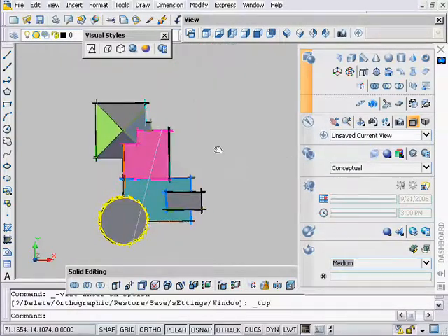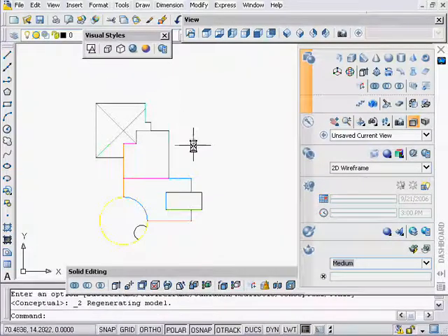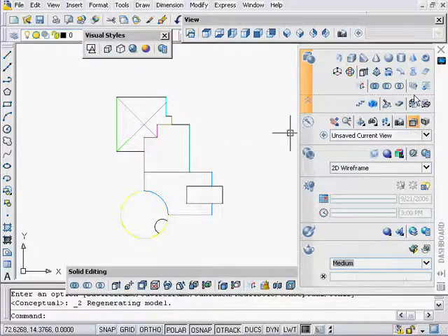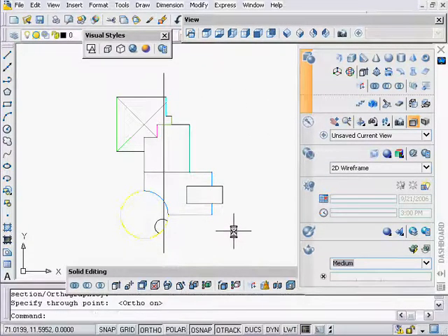Now, maybe you just want to keep it real easy. Go to the top view. Click on here, delete that. Maybe you're in just good old-fashioned wireframe. Okay, go into here. On the right, on the control panel of the dashboard, section plane. And just click on here, turn your ortho on, pick a point, and you're done. That's it.